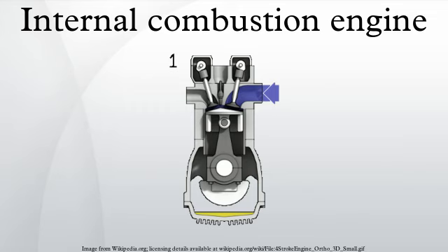Some ignition systems are capacitive discharge types. CD ignitions use step-up transformers. The step-up transformer uses energy stored in a capacitance to generate the electric spark. With either system, a mechanical or electrical control system provides a carefully timed high voltage to the proper cylinder. This spark, via the spark plug, ignites the air-fuel mixture in the engine's cylinders.